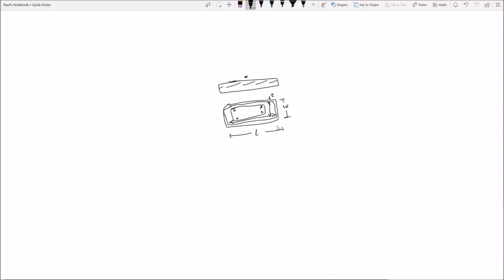If you're planning to put screws in here, you want to keep that in mind, because screws need a base to sit on. So this base, in the side view of your enclosure, needs to be something like this so that the screw will go in here. You need to have studs in here to receive the screws. All of them need to be aligned with the screw holes in the PCB, for example. So you want to keep that in mind.